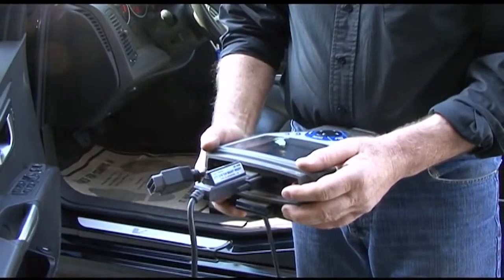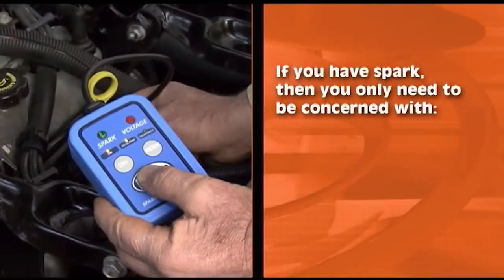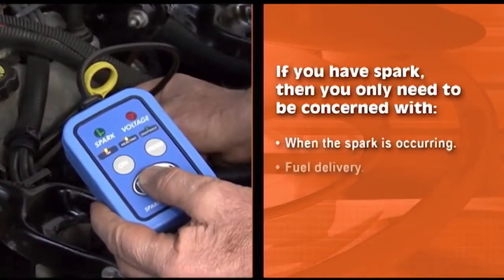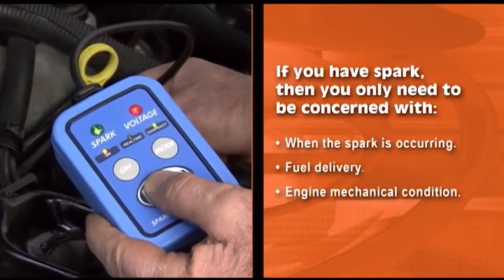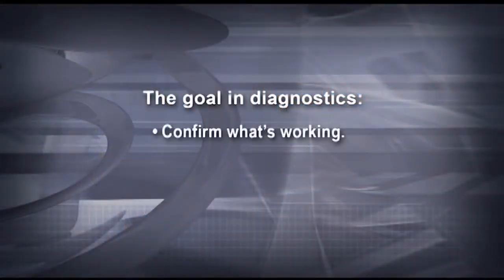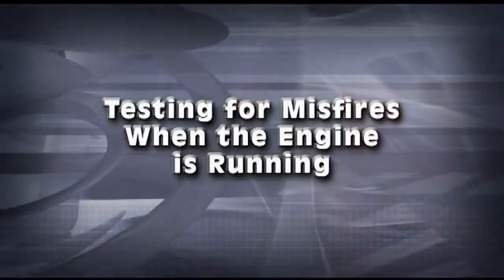If possible, use a scan tool to command the powertrain control module to fire the ignition coil for testing. If you have spark, then you only need to be concerned with when the spark is occurring, fuel delivery, and the engine's mechanical condition. The goal in diagnostics is to first confirm what's working, then you only need to test what isn't. We can cover more fuel-related and engine mechanical diagnostics in a future series of videos. For now, let's go back and talk about testing for misfires when the engine is running.